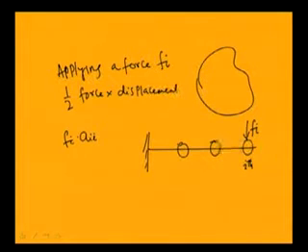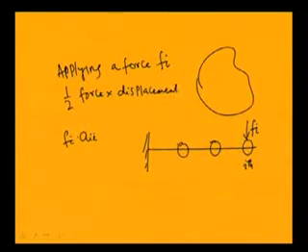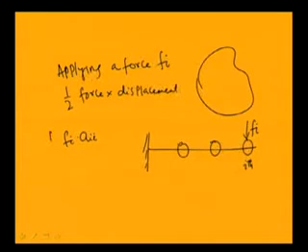So due to a force Fi applied at the ith position the displacement will be Fi into Aii, and at other places the force equals 0. The work done will be equal to the summation of force and displacement at all these places. As the forces at other places are 0, the work done will be half into the force Fi into displacement Fi Aii. So this becomes half Fi square Aii.